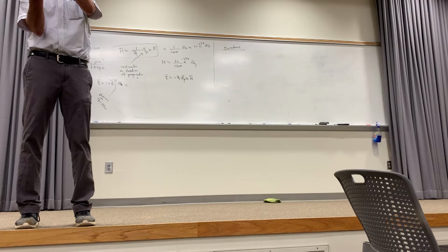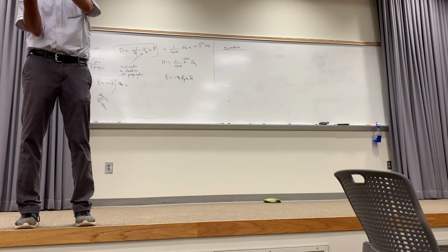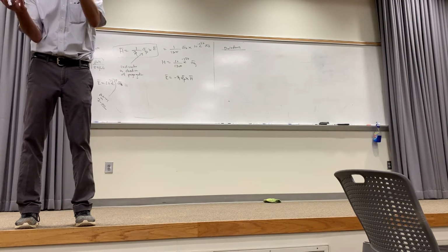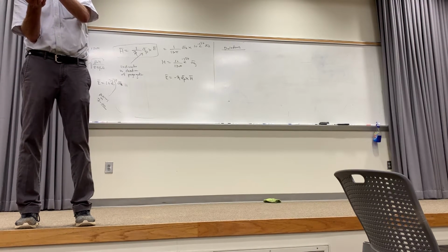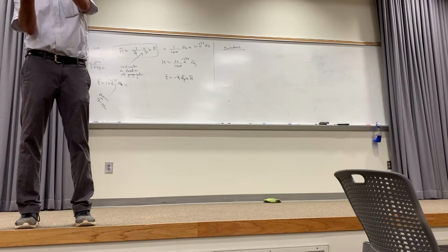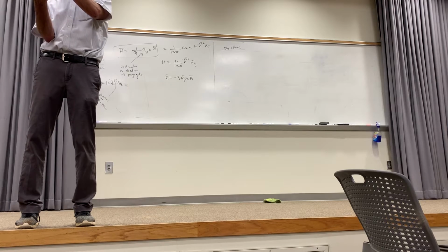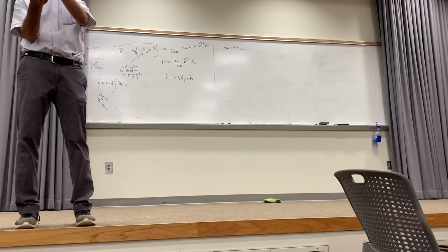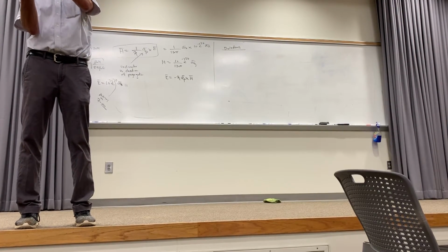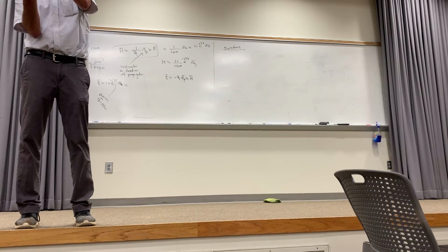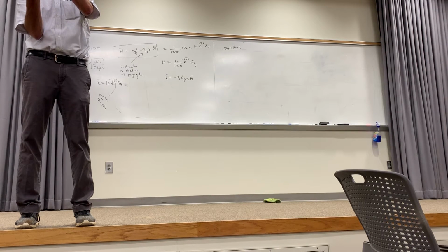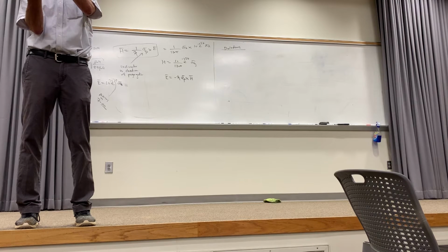To make a long story short, resistance is proportional to 1 over conductivity. So 1 over 10 to the 7th is 10 to the minus 7th ohms, of that order. Just hang on for a second. Compare that to the atmosphere. Here, we've got a conductivity of about 10 to the minus 14th. All right, 1 over 10 to the minus 14th is 10 to the 14th. It means over that same area, we have about 10 to the 14th ohms, an immense amount of resistance, right? But there's still enough that a little current will leak through there.